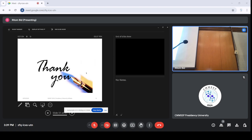Yeah, the 14.5% is the maximum reported efficiency in CZTS solar cells. So normally the solar cell structure uses the substrate configuration. That means the CZTS layer is on the substrate, and on top of that we have the buffer layer and window layer. The window layers are basically the transparent and high bandgap semiconducting layers, mostly oxide semiconductors.